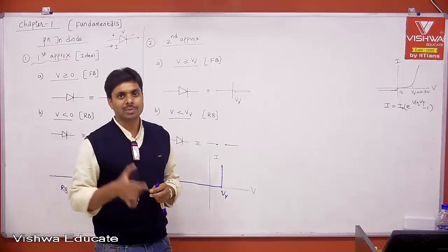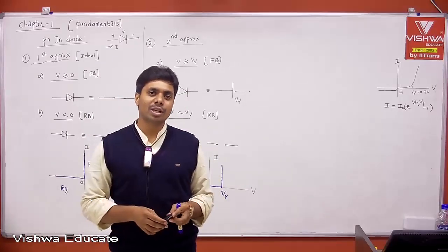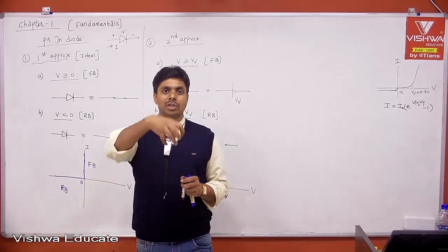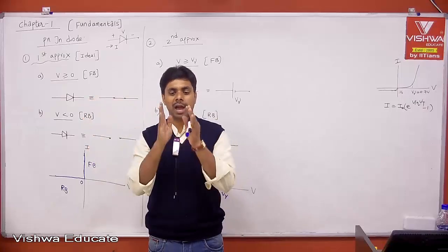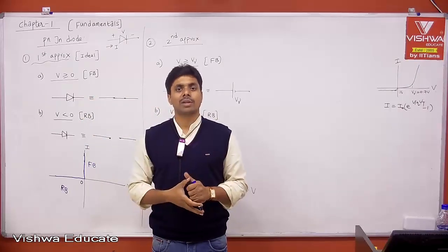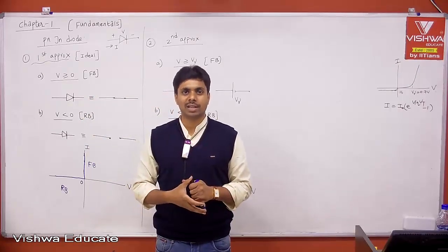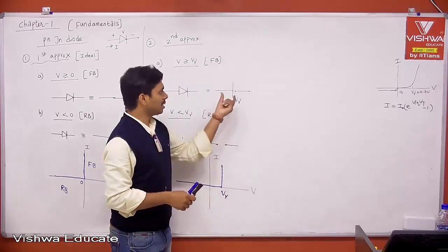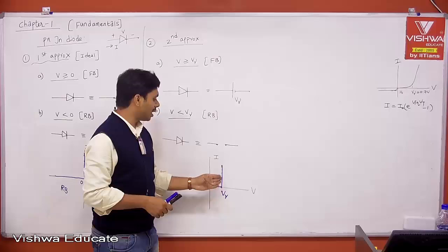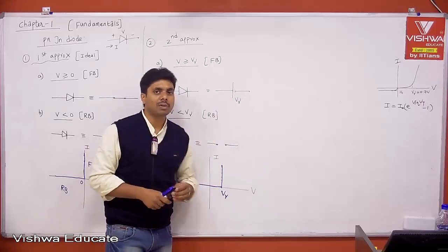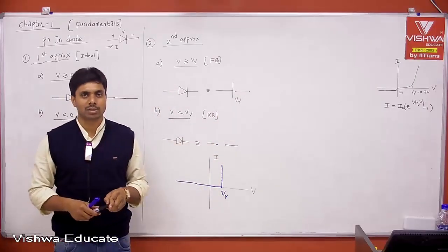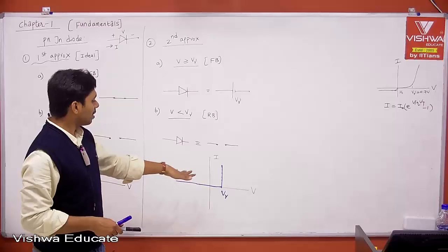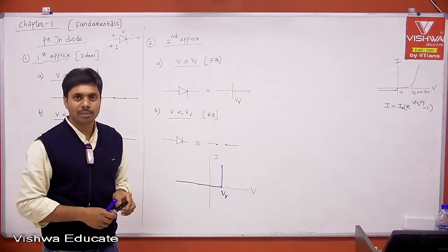We know that. I already explained the ideal voltage source. What is an ideal voltage source? Whatever the current you draw from your voltage source, it has to have the required or defined voltage, right? It can support any current, but it has to have the voltage. Similarly, when you represent it with a battery, it can support any current, but with a voltage drop of V gamma. That is what it is. Okay. Now, this is somewhat close to our exact model.